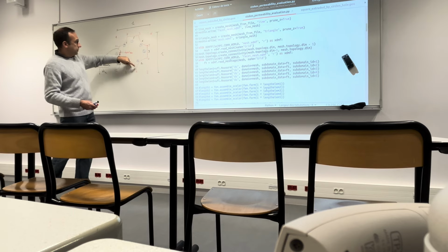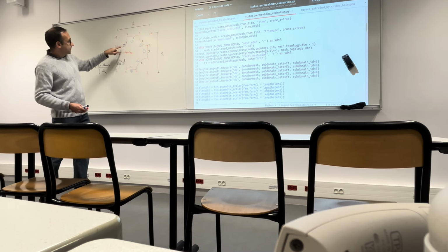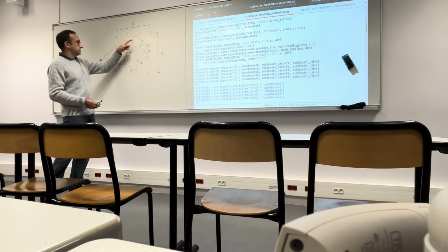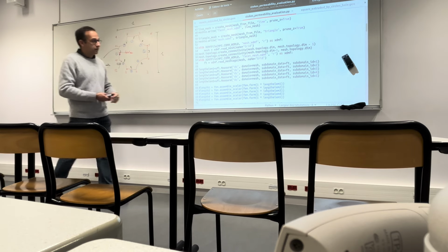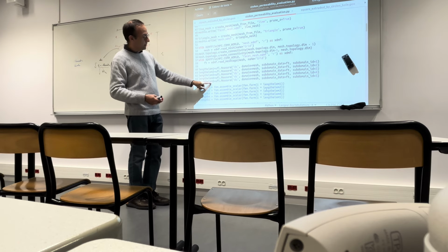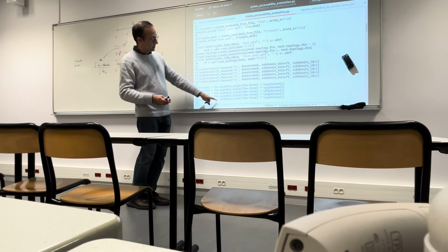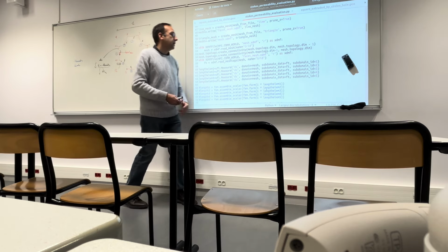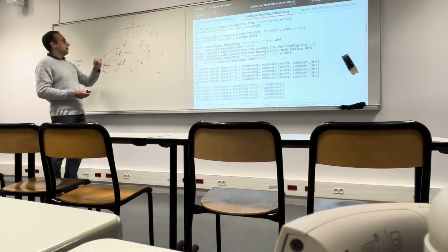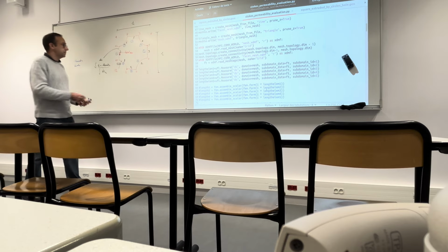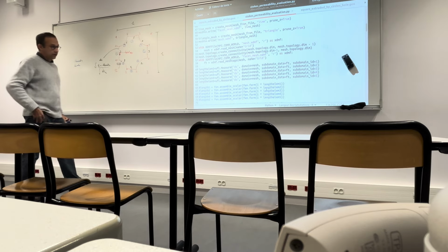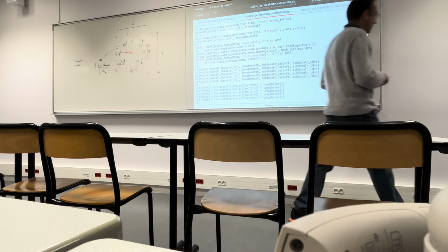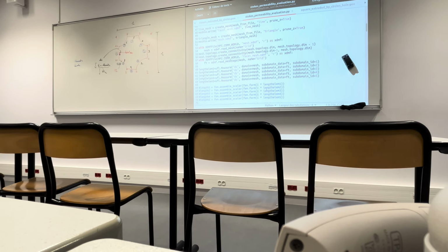And so this has been done for the 4 subdomains 1, 2, 3, and 4, and also for the 5th part, which is constituted by this 4th of circles. And so in the end, what you should recover from this length element 5, and in particular from this FEM assembly scalar of FEM form 1 times the length element 5, is the length of a circumference of radius 0.25. Okay, and in fact this I checked, and it works.